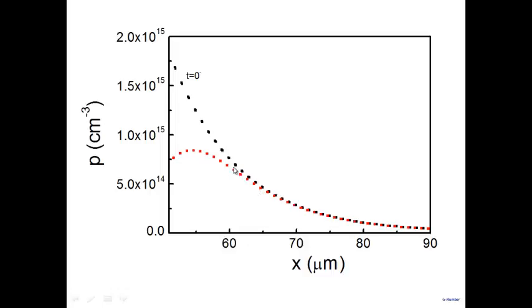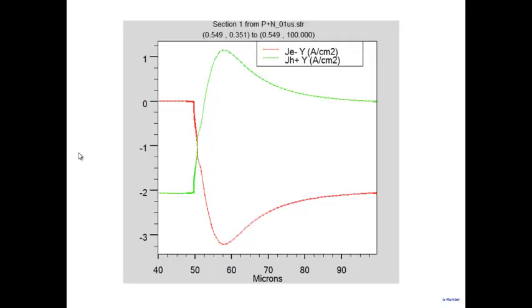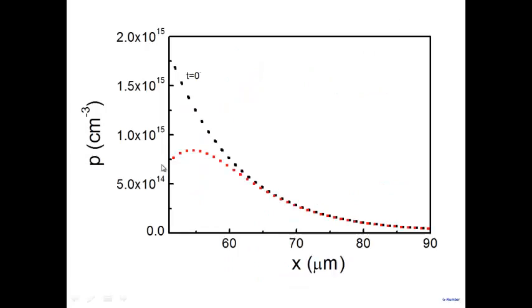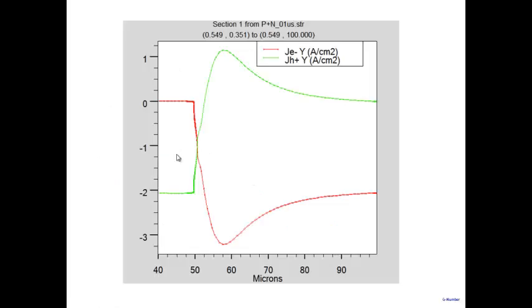They'll all recombine. So what is happening is the holes are going towards the right, and they're all recombining. And when they're going left, they're going into the P plus and flowing out through the external circuit. If you look at this hole density here, and look at the current, the current is simply the derivative, because hole current is predominantly diffusive. So look at the green line.